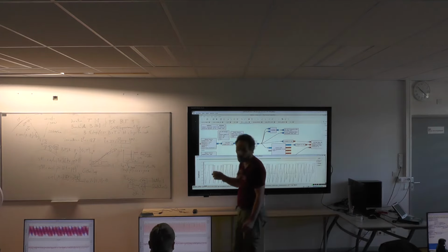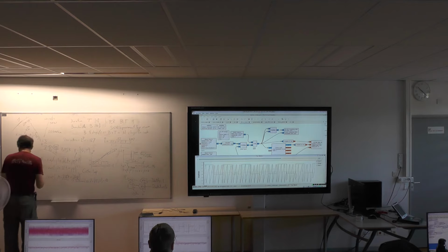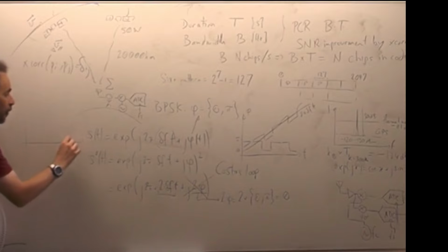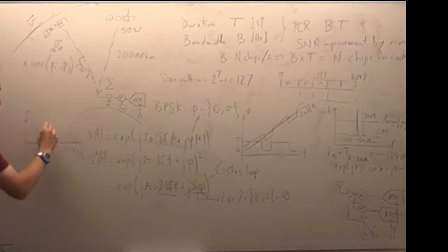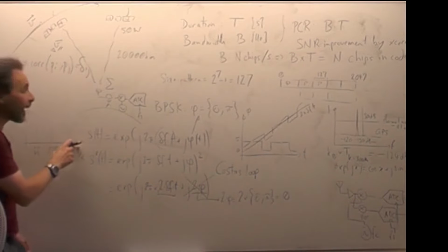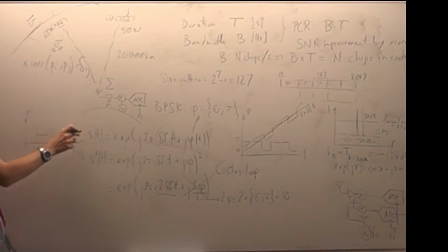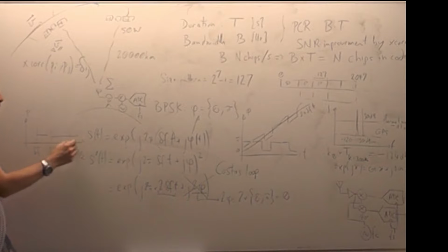You still have a leftover frequency offset. Why is it? Well, remember in our example here we said we are squaring the signal. So what does squaring the signal mean? It means that if I have a delta f over here, when I square the signal, I'm creating a spectral component at 2 times delta f because I'm squaring. But your discrete time signal processing can only work up to the Nyquist frequency fs over 2. So if you're moving delta f too far to the right, you see that 2 times delta f moves to the right twice as fast, up to a point where 2 times delta f might reach the Nyquist frequency and actually get aliased.